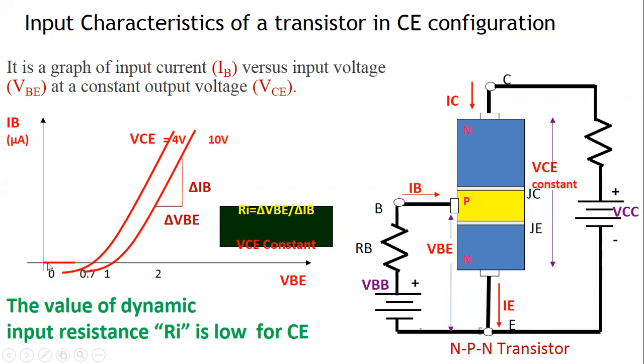This red line, we see, is not exactly zero. It is something very minute, in the microampere, 0.01 microampere, nanoampere range. That very minute current means no operation is happening within this device. We can consider the device not in working condition, because it doesn't have enough current for the circuit to be driven. So before this threshold voltage this device is off, but after we apply the threshold voltage of 0.7 volt, this device turns on and the current starts to flow in a linear fashion.